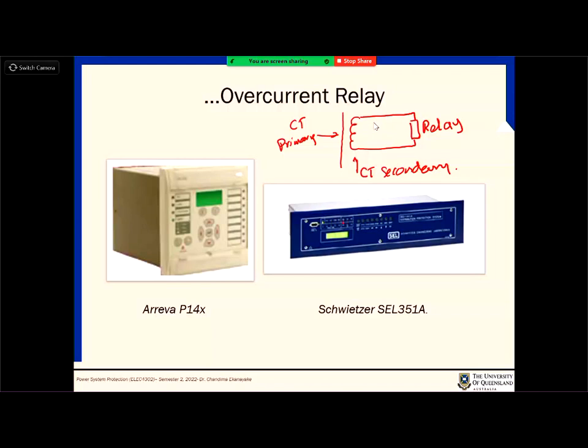So if you look at it in the substations or in the laboratory environment, you will see the same. They usually keep it as a closed circuit. So when you are using a CT, before connecting the load across it, it should be short circuited. And then once the load is connected, you can take the short out, because the load has a small impedance, right? So if you just take it out without a load, that could generate a huge voltage, right? So remember that.